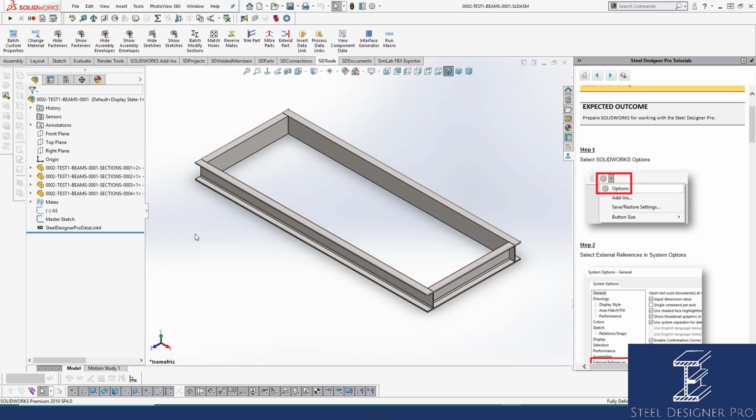Now, our attachment sketch, I've forgotten to do this. You should always grab your attachment sketch and drag it up to the top, because everything is top-down driven in SolidWorks. Okay, so now that's been added to the top, and all the components are hanging off that item, so that when it rebuilds, it will rebuild down the tree. All these items are now attached to my sketch, so that when I change my master sketch, which is what I'm also going to drag up as well, and just be mindful that sometimes you get a little bit of delay. I'm just waiting for it to, yep, okay.